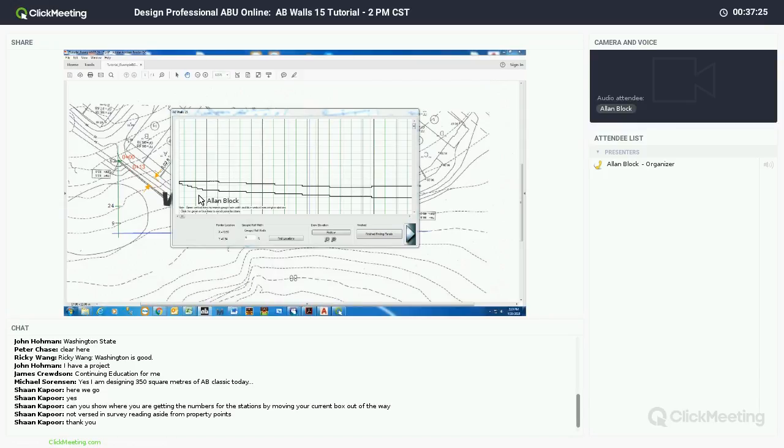So what I mean by that is I'm going to select this second green line from the left, and if I look at the bottom of wall, I have 3 step downs of our bottom of wall. So that's by my 3 elevation changes. That way I can take a conservative approach and design for the tallest point of that section. That's going to represent the whole panel.